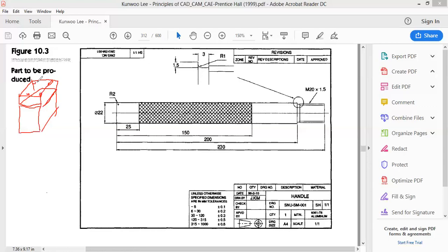So they have to make use of a torque wrench. They have to maintain the torque only, right? So what should be the torque that has to be used will also be mentioned on the drawing sheet. Then will come which should be the next part that has to be assembled, how much it should be tightened, how it has to be moved, and how the alignment has to be checked. All those details will be mentioned in the operation sheet, along with the assembly drawing that is going to be provided for the assembly department. Okay, right? So this is how the operation sheet is going to be.